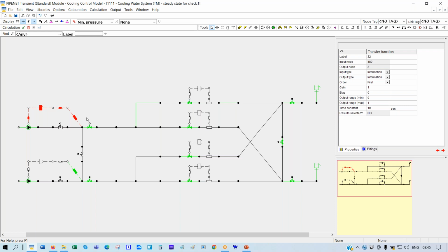Because if the pressure at the inlet of the transmitter changes, the output signal from the pressure transmitter does not change immediately. It takes time to respond. And the transfer function models that. The PID controller is here. And I'll come back to that in just one moment. And there's another transfer function here, which represents the dynamics of the pump. Because the PID controller tells the pump change speed, the pump doesn't say yes sir and change the speed instantly. It has its own dynamics and it'll take time to respond, and that's why we have the transfer function.